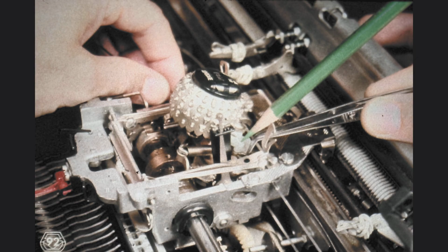Once again, in order to remove the anchor screw, we must first remove the rotate spring tension from the rotate tape. We do this by rotating the element counterclockwise approximately 1/4 of a turn, then half cycling a character so the rotate detent can lock the element into position. Take the time you need to complete this.